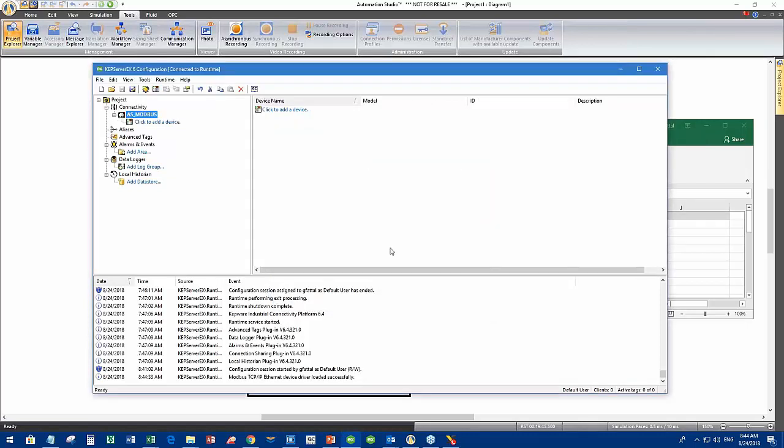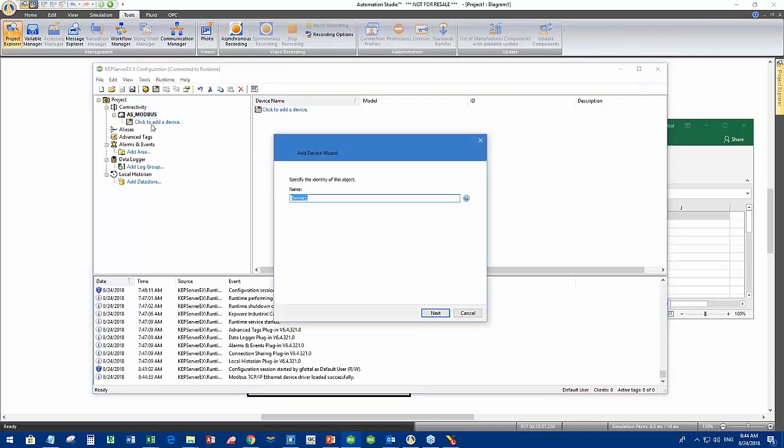Until I go and finish everything. Now, once I define the channel, I can communicate by Modbus TCP with several PLCs. It's not only one. On the standard, I can communicate with hundreds of them. So here I have to give a name to the PLC that I want to talk to. So this comes to adding a device. So I add the device. It gives it a default name, device 1. So I'm going to call it PLC 1. Next. And then I go on here.